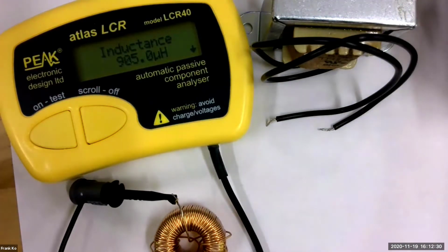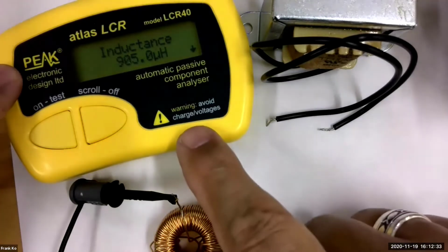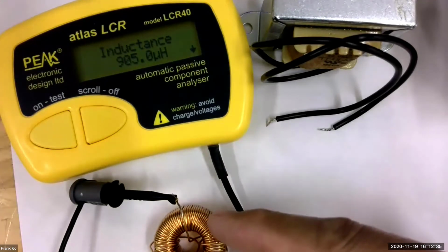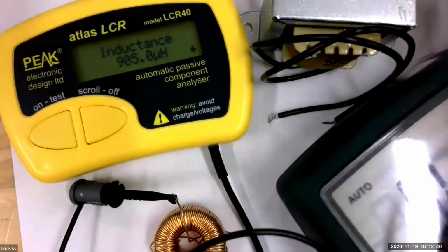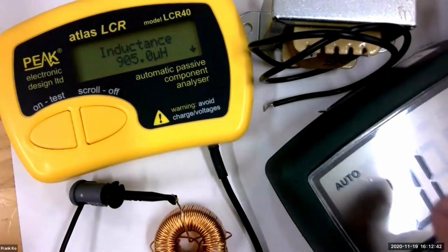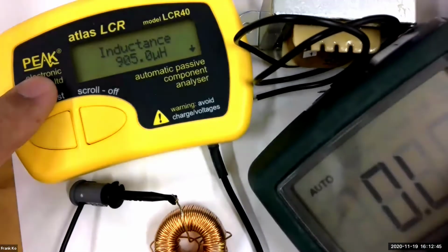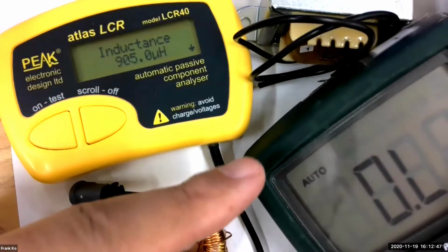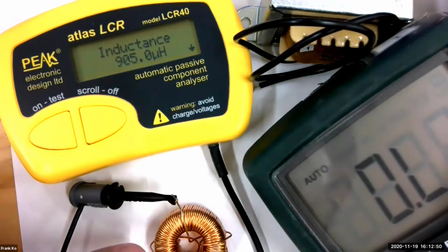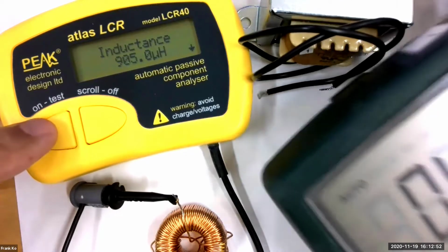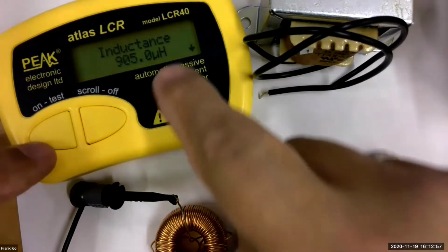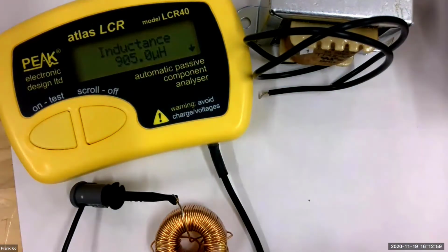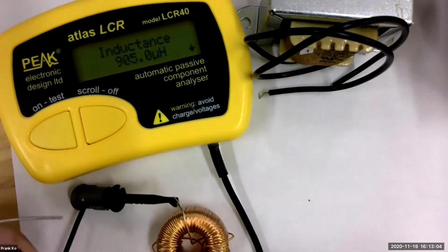So that is a characteristic that this little device can test: the inductive behavior of this coil. The digital multimeter only shows us DC resistance of the wire. So you see how these two instruments are different. The digital multimeter measures only the DC resistance of the wire, whereas an inductance meter will actually measure the inductance of these coils in terms of their value in henries, millihenries, or microhenries.